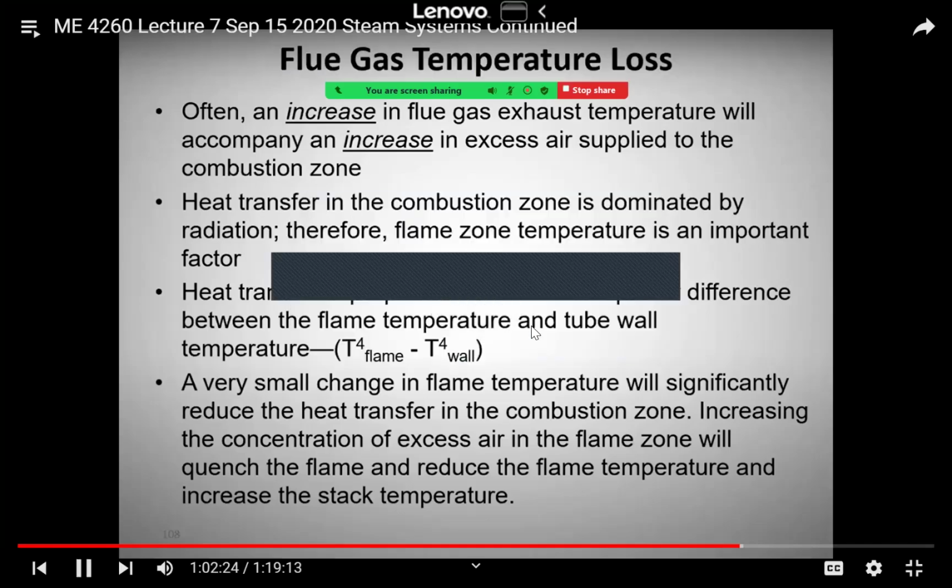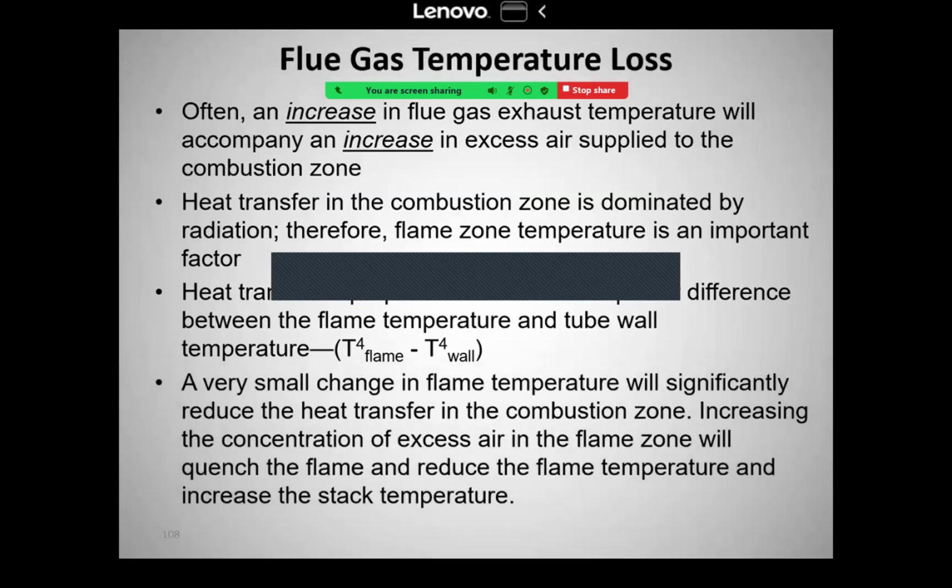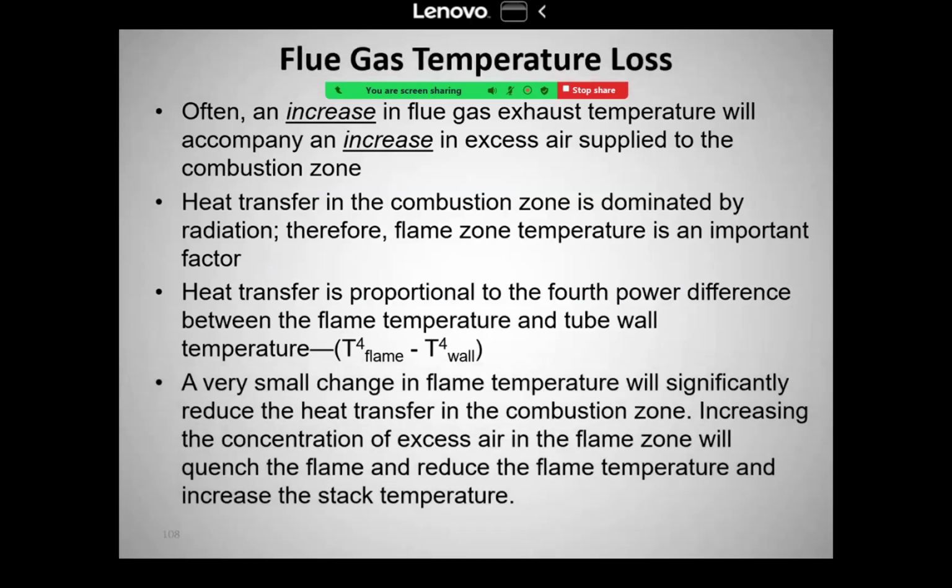the amount of combustion. Everything else stays the same, still 50% load, but the damper control on the fan goes wacky, and we're putting in more air than we should. Okay, so that will typically increase the flue gas exhaust temperature. And so here's what's going on.